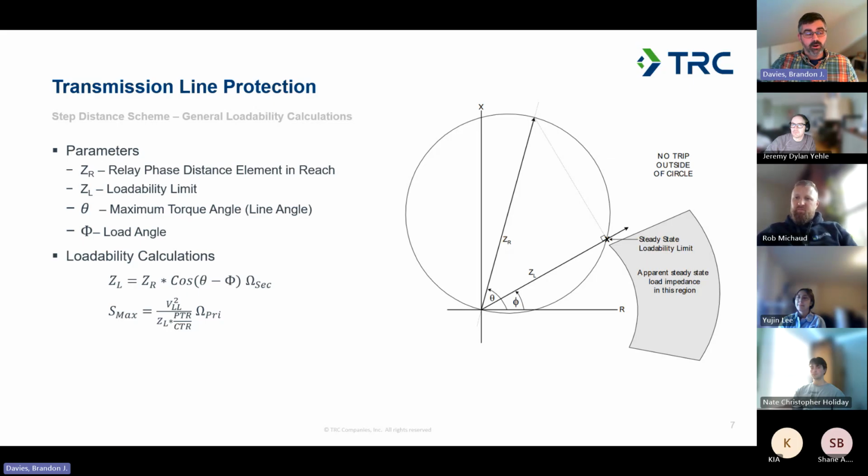So right now, how we've always done it is you have these winter ratings and summer ratings. Summer it's hot, so you can't push as much power through the system. Winter, especially up here in Maine, acts as a really nice heat sink to absorb the heat out of the conductor, so you can push them a little further. There are a bunch of different things utilities can do to meet this requirement. They're really still figuring it out.